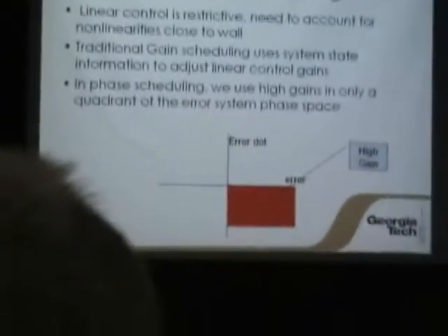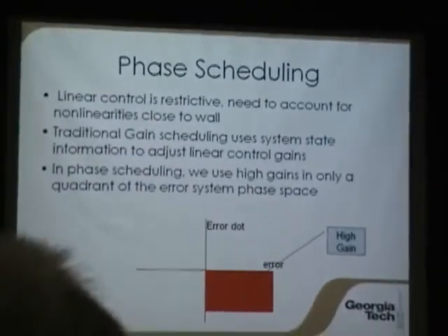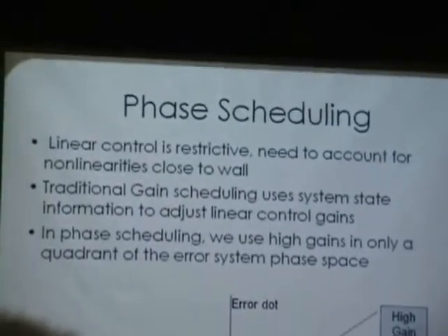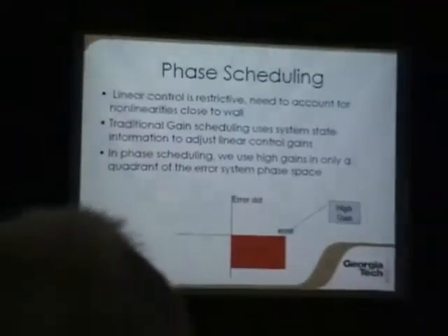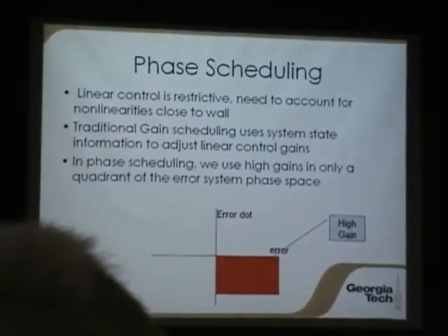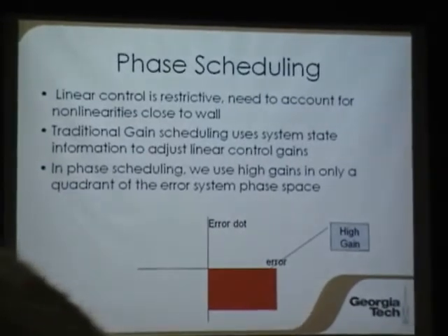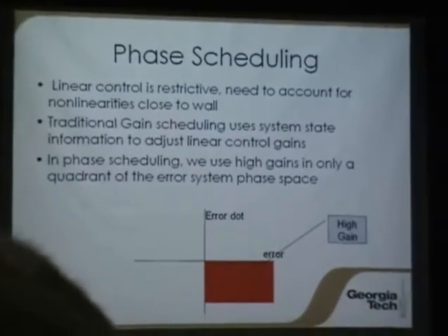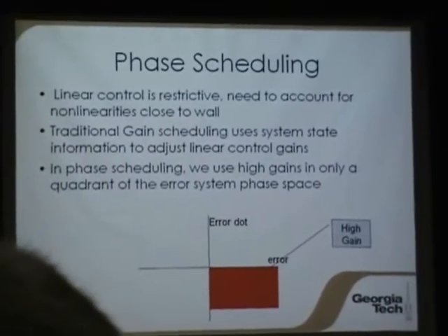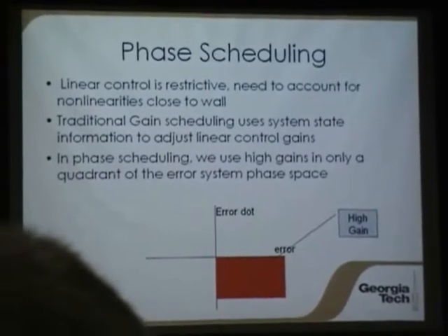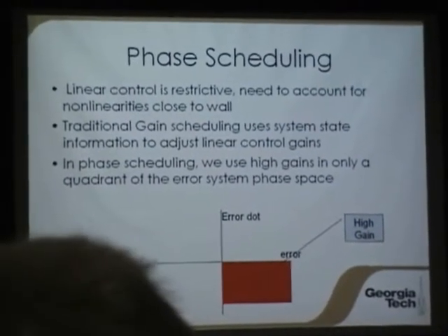Our pilots describe that as basically, if you're a little bit away, the wall is trying to push you. And if you cross a certain boundary, then the wall tries to pull you towards it. So there is some kind of non-linearity there, and the whole assumption in PID control is that everything is linear. So we need to account for this nonlinearity with something.